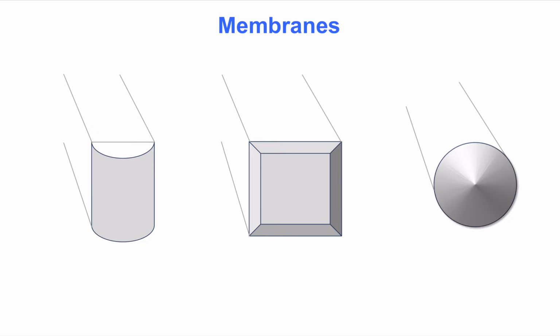The stress function in the middle of this slide satisfies the boundary condition because it is zero around all edges of the cross-section. This stress function is used for hollow rectangular cross-sections because it satisfies the boundary condition also on the inner edge of the cross-section walls. We see that this stress function is constant around the edges of the cell of the hollow cross-section, which does indeed satisfy the boundary condition. The stress function on the right-hand side looks like a cone that is zero around the edge of this circular cross-section. It would have been even better to visualize a similar shape that looks more like a bubble, with continuously varying derivative, because that is a commonly used stress function.